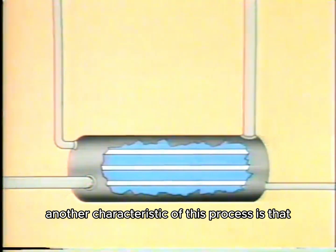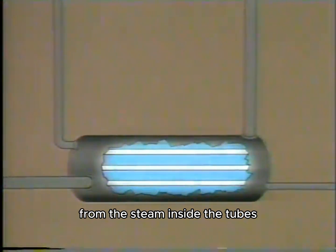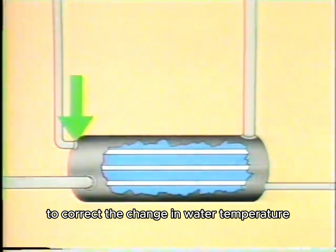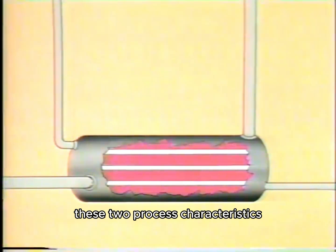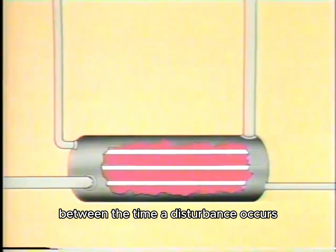Another characteristic of this process is that the steam tubes resist the transfer of heat from the steam inside the tubes to the water outside the tubes. This means that if steam flow here increased to correct a change in water temperature, there would be a lag between the time the steam flow changes and the time the water temperature changes. Now, these two process characteristics, capacitance and resistance, cause a significant lag between the time a disturbance occurs and the time it's sensed and corrected.